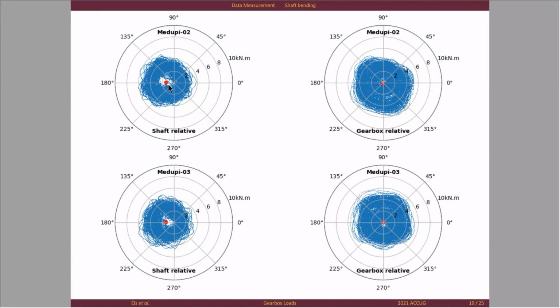unbalance. Now the unbalance can be two things. The one is the mass or the inertia of the blades, and the other one is the aerodynamic unbalance. In other words, as the guys install the blades, it's not necessary that they all have exactly the same angle of attack.